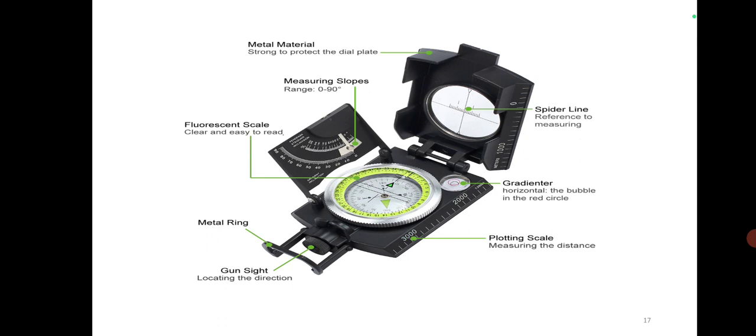Okay, and so clinometer, basically if the difference between clinometer and Brunton compass is asked as a part A question for 3 marks, you just need to write the basic differences. Clinometer for measuring angles of slope, elevation or depression with respect to gravity. It has a tilt indicator. You get the gradient, that is the positive slope or negative slope, and the unit is degree, percentage or topo.